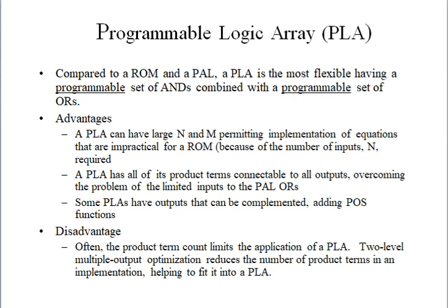read-only memory. A PLA has all of its product terms connectable to all outputs, overcoming the problem of limited inputs of PAL. PAL means Programmable Array Logic. Some PLAs have outputs that can be complemented, adding POS, product of sums functions.